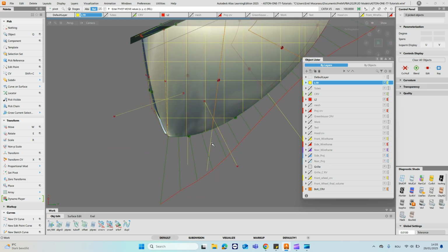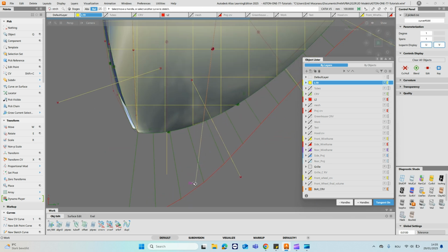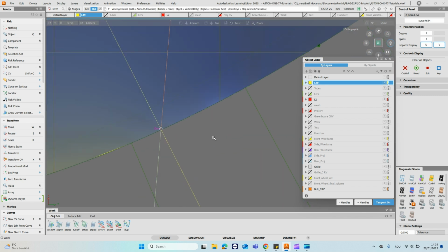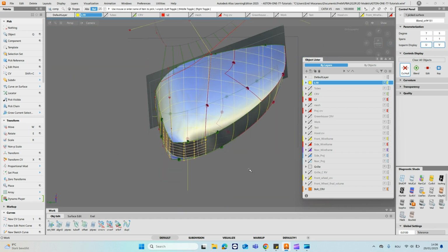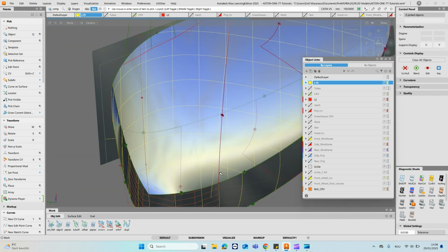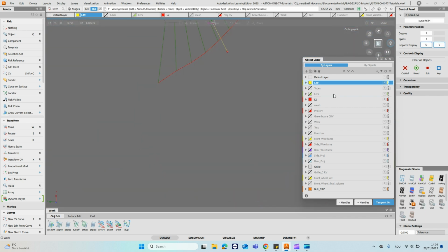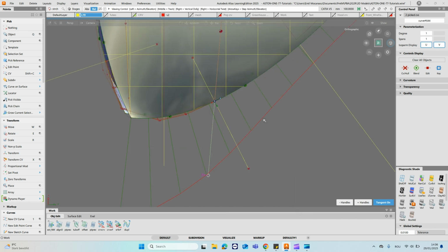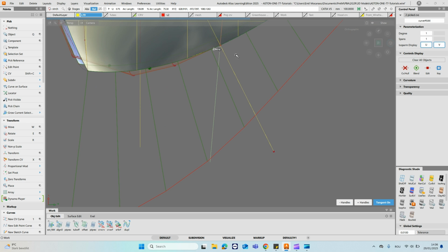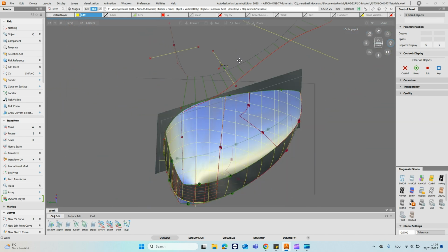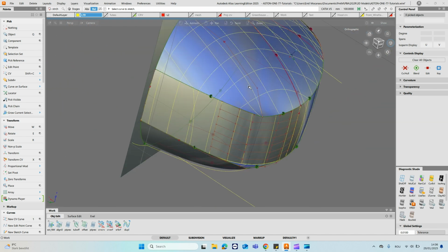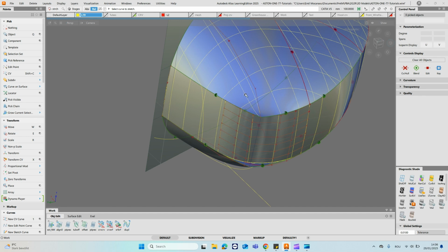I will want to line this curve up in such a way that that end comes there. So I'll stretch it a little bit. Turn on the CVs on this so I can actually snap that curve where I want it in a projected manner. Taking that handle and snapping it to that point so we know those will line up. And around here, that's okay.